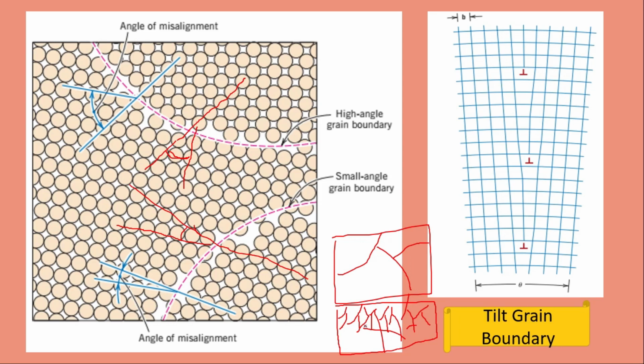Second thing, when a dislocation moves, obviously this is a single grain, so it has crystals in it in the same orientation. So let's suppose it has a dislocation here, a half plane edge dislocation, and that dislocation is moving towards the right, and it keeps on moving towards the right until a grain boundary arises. Now the atoms are no more arranged like this, instead atoms are arranged like this. So the dislocation has no way to move forward, right, because the orientation of atoms in the next grain is creating a hurdle. They are acting as an obstacle, which we discussed in the beginning, that in the absence of an obstacle a dislocation can move easily, but when we have an obstacle like this grain boundary, the dislocation cannot move, or at least it cannot move easily. So grain boundaries act as an obstacle for the dislocation, for the plastic deformation as well.